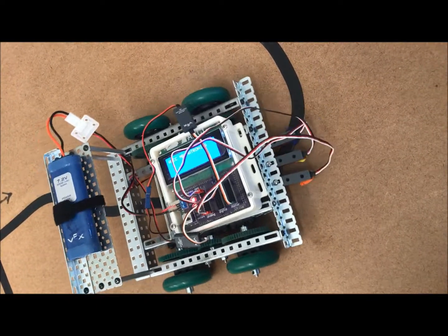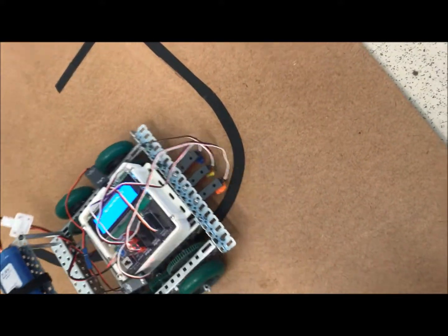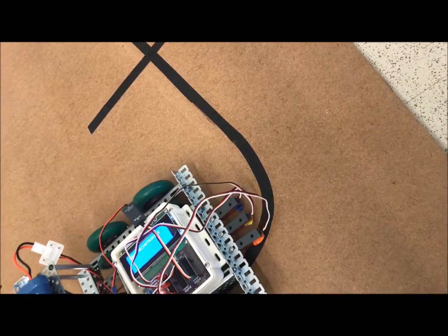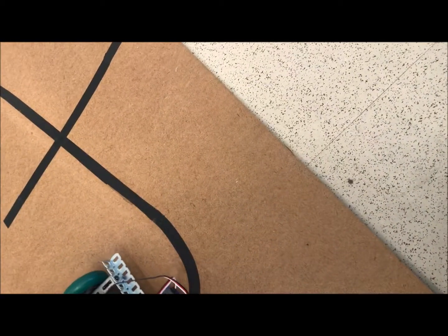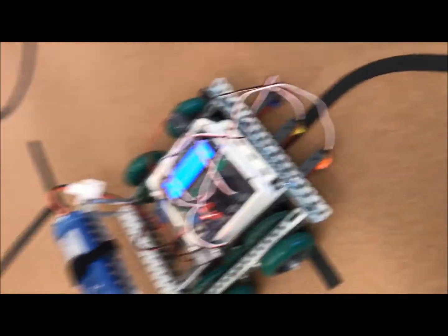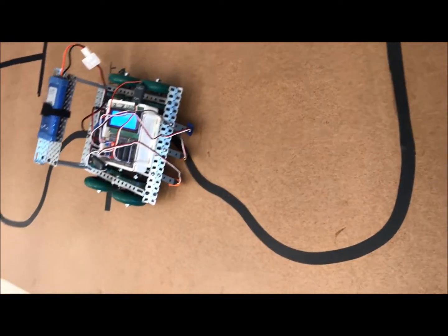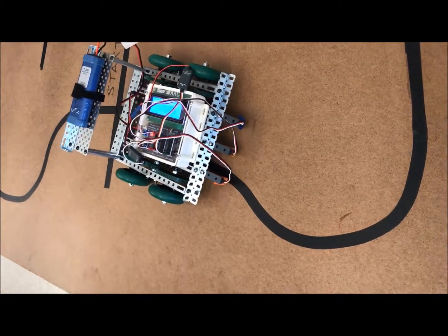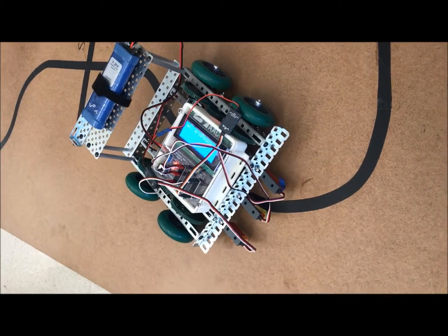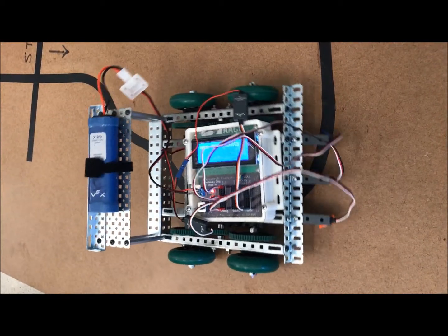And I thought I would be able to manipulate the code by just adding certain delays, saying okay, well, if the robot has to turn left and it needs to be sharper, then I'll just add a delay to that, and it would just make so many more mistakes, because then it would also apply to the right, for all the sharp right turns. So definitely the spacing of the trackers. After a while, I did figure out that instead of them being further and further apart, they need to be closer and closer together. It wasn't until I got them touching each other that I was able to get the most accurate steering when it comes to the turns.